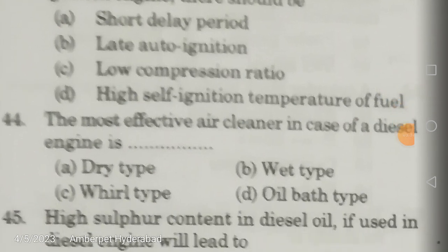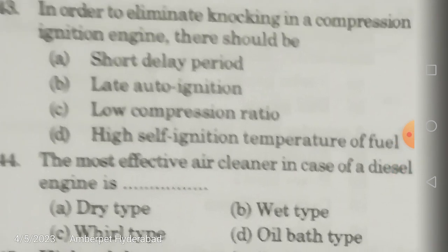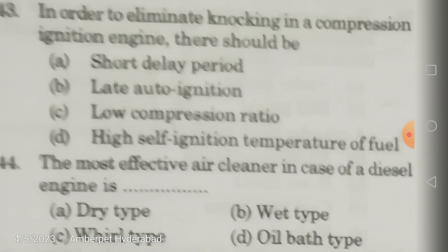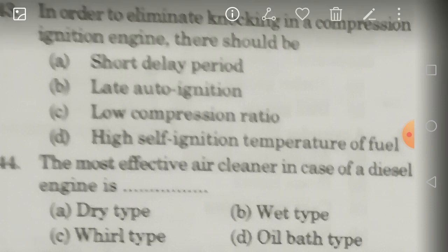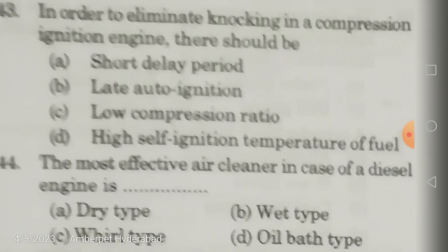All right. So the phenomenon of knocking is different in the different engines, for example, SI engines and CI engines. In the SI engines, it is the last charge in the combustion chamber that is going to detonate or be subjected to knocking. Whereas in case of diesel engine, it is the initial or fresh charge, the front charge at the TDC, which is going to result in the detonation or knocking. Actually, the basic reason for this is that the combustion phenomenon in both the engines, SI and CI engines, are totally reversed, opposed.